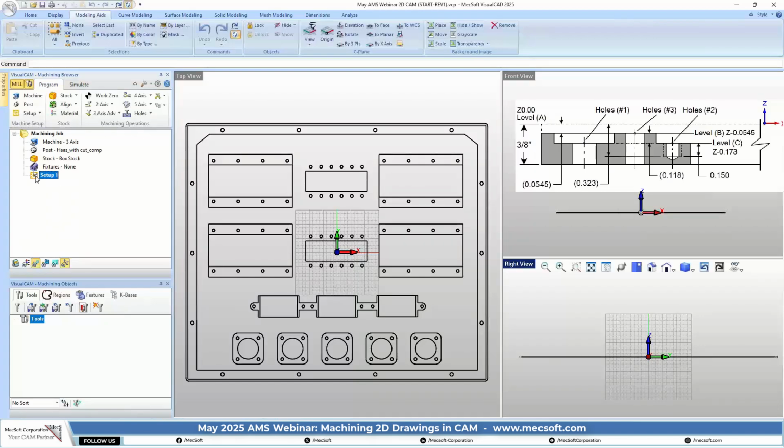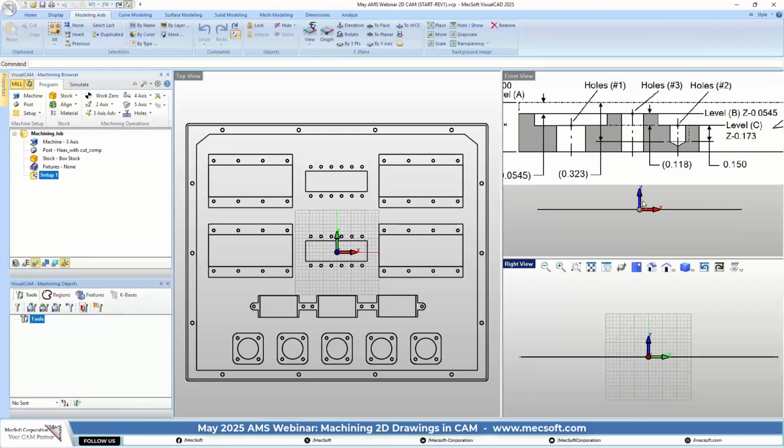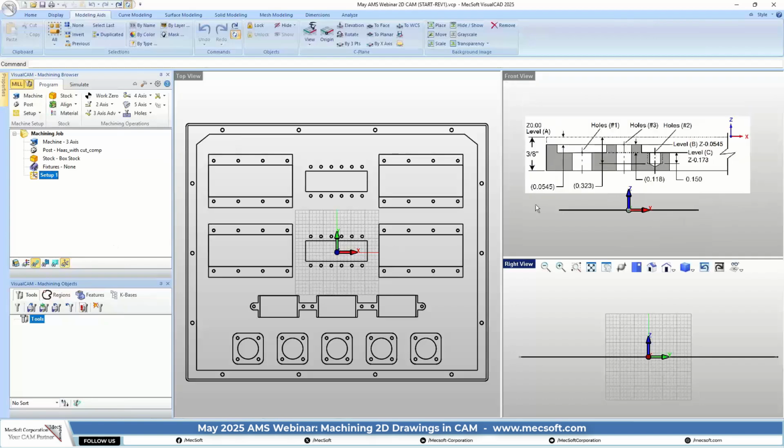And that orientation setup is on the XY plane. You can see the arrows here for X and the Y. And down here, you've got a little toggle where you can turn off the machining coordinate system. By default, the machining coordinate system is aligned with the world origin. So we can just leave it off or on. It doesn't really matter.